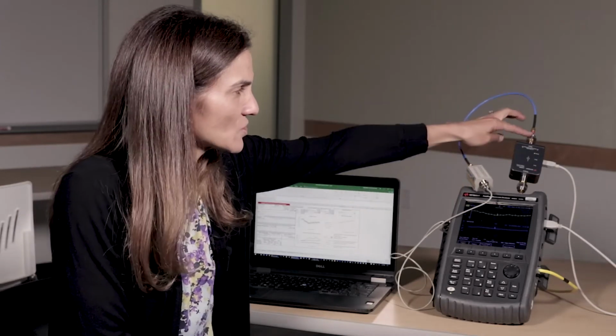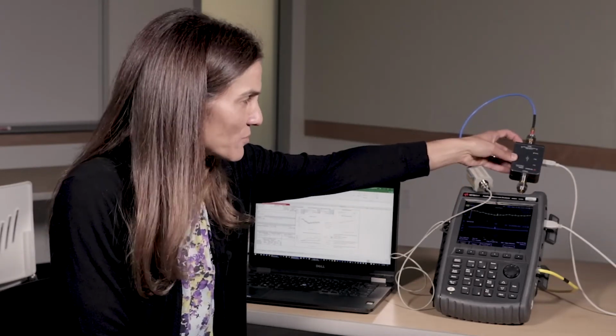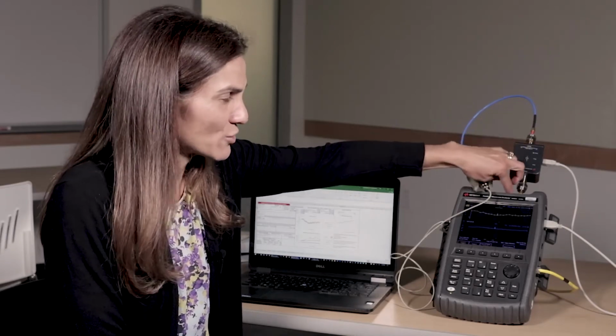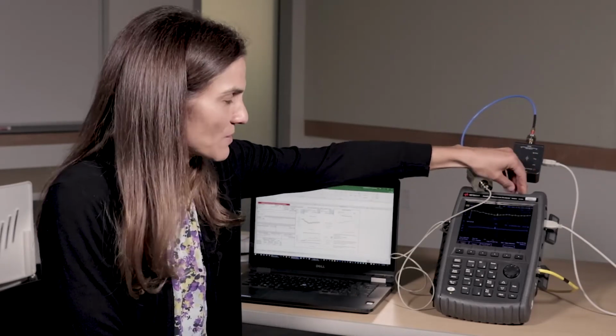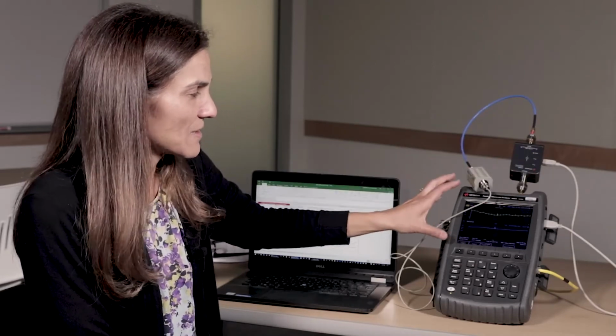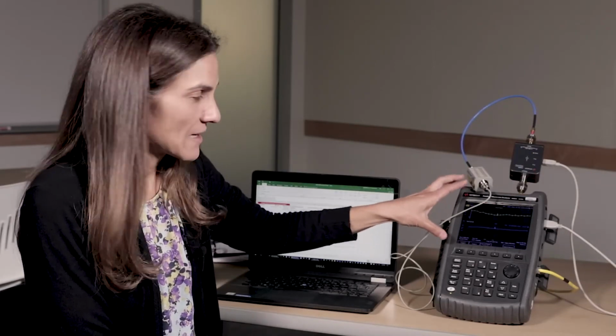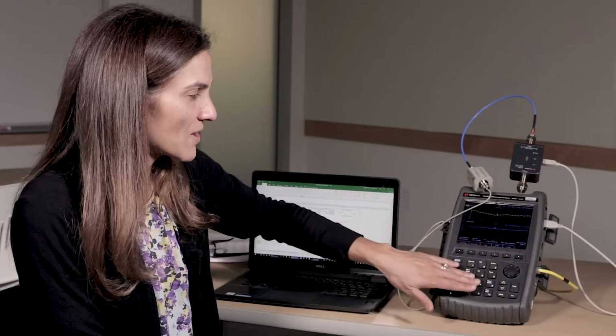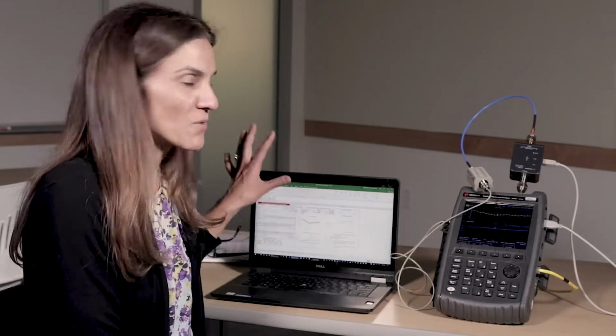The output of the noise source goes to my amplifier or my DUT, and then from there it hooks up to FieldFox's port 2, which is the port 2 SA receiver for the noise figure measurement. And I've set it up to measure noise figure and gain, and I'll be looking at the uncertainty here on the FieldFox and also again doing the analysis on the computer. So with that, we'll go ahead and we'll start with the Excel, which is the tool I think a lot of people will be using.